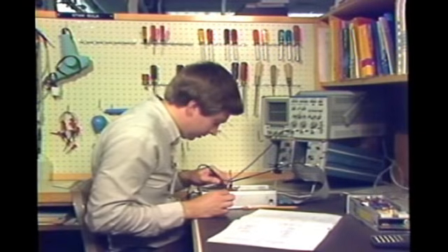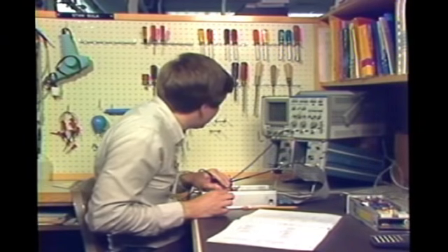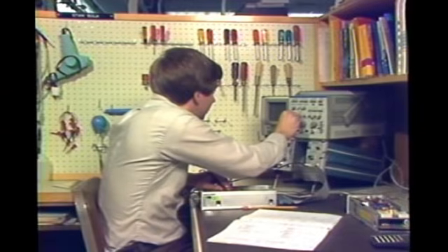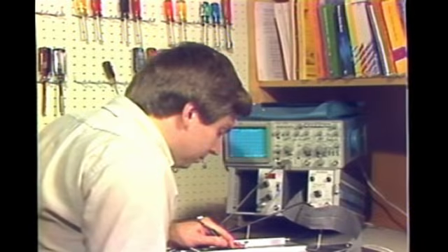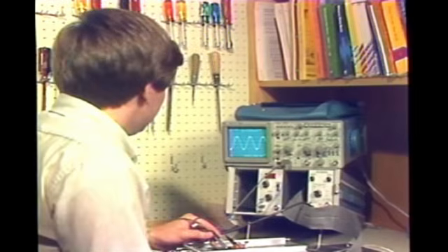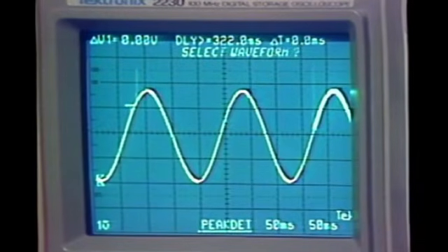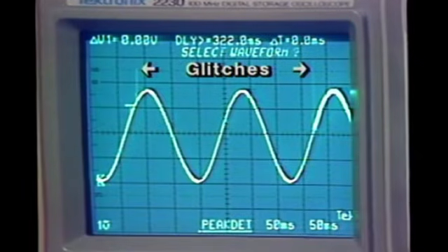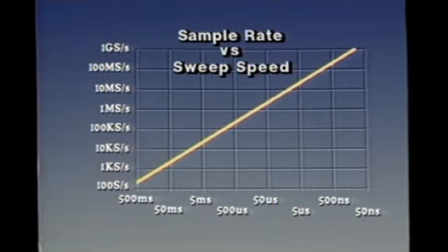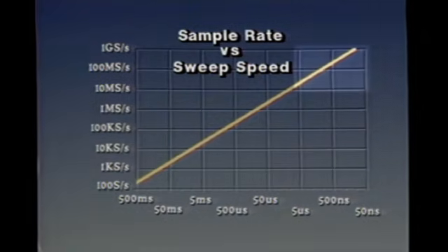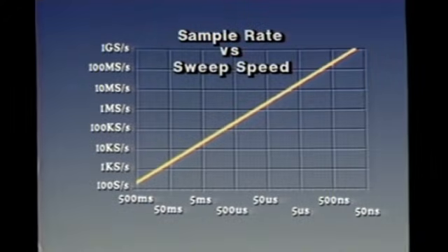A common problem associated with digital storage oscilloscopes is missing signal details that occur between samples. A DSO sample rate is the major limitation in capturing narrow glitches or noise spikes. To guarantee the acquisition of a sample, the glitch must be wider than the sample interval. If it's narrower, then it probably won't be sampled. As discussed earlier, a typical digital storage oscilloscope uses the specified maximum sampling rate only at the fastest time-based settings. The sample rate decreases significantly at slower time-based settings.